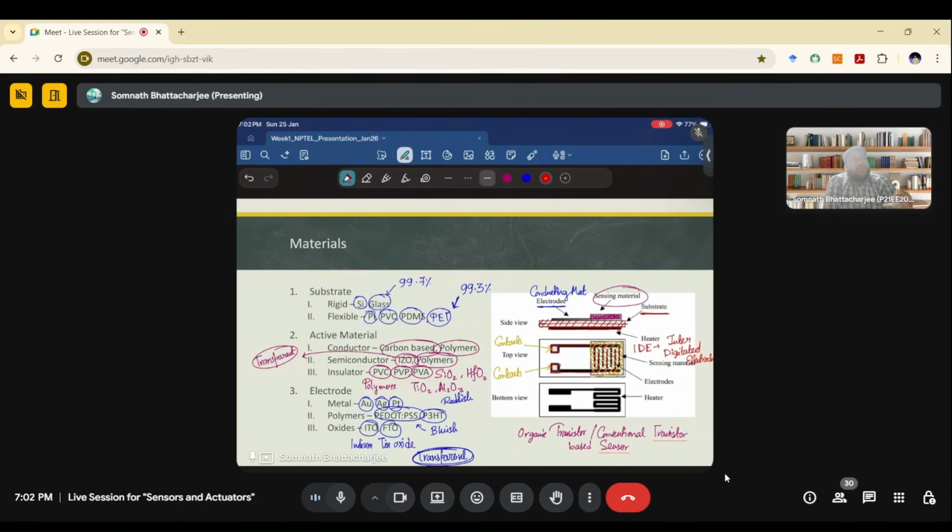And also for these CVD or PVD techniques, you need a very high vacuum as well. So achieving that vacuum also requires a very large energy consumption. So you don't need that as well. So if you are moving towards a very low cost thing, you can utilize polymers as well. So based on your use case, you need to choose a specific material, you need to choose a specific equipment to use, and you also need to define what parameters are important for you.